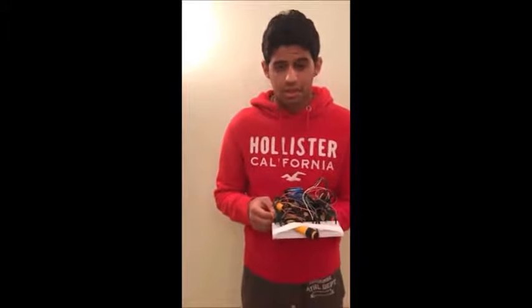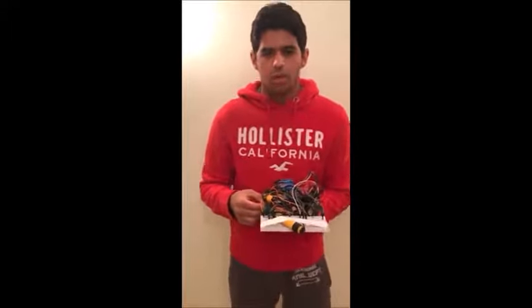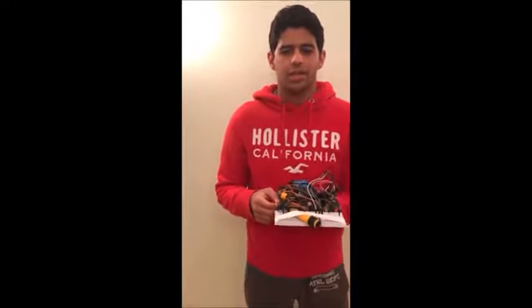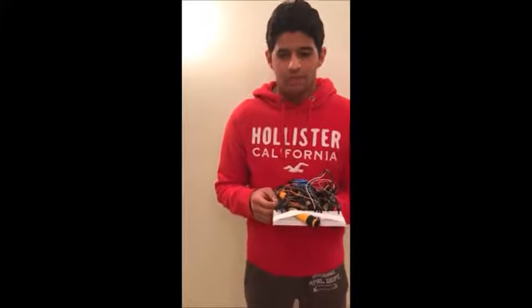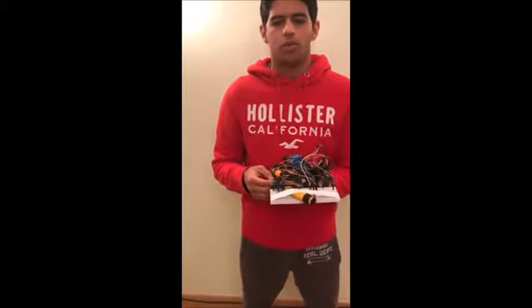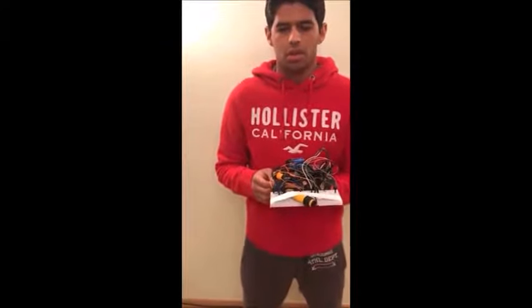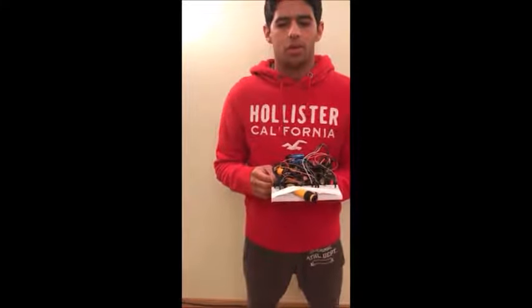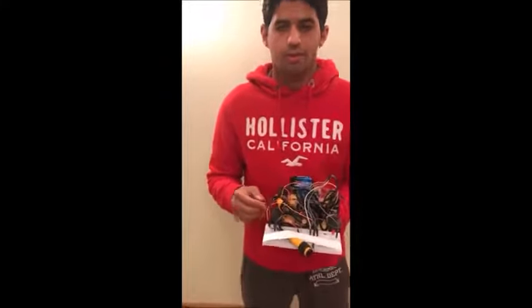The sensor calculates the distance to the first object it detects by calculating the time between the pulse emitted and the pulse received, knowing that of course the transmitter and receiver in our case are at the same location. After calculating the distance, we check if it is less than 50. If it is more, the car will proceed to move forward normally. If it is less, the car will reverse the motion of two of the DC motors connected to the tires for the car to move backwardly in a different curved line until the condition forces it to move forwardly again, meaning that there are no obstacles. This whole cycle keeps repeating for the car to proceed moving forward without hitting any obstacles.